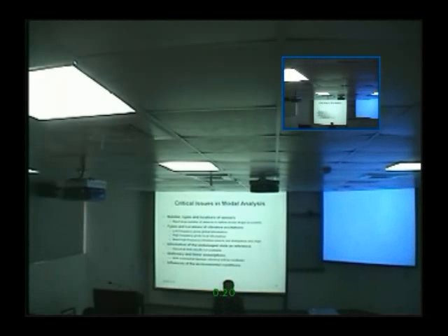So they went out and tried to detect damage of the bridge. They found all kinds of problems. One of them is the temperature. They were in New Mexico, and New Mexico is a desert. In the evening, the temperature can drop very low, and during the day, the temperature rises extremely high. The fluctuation of the temperature can be more than 20, sometimes 30 degrees during just one day. So that is another problem. And not only do we need a large number of sensors, but we also need to consider where we put the sensors.